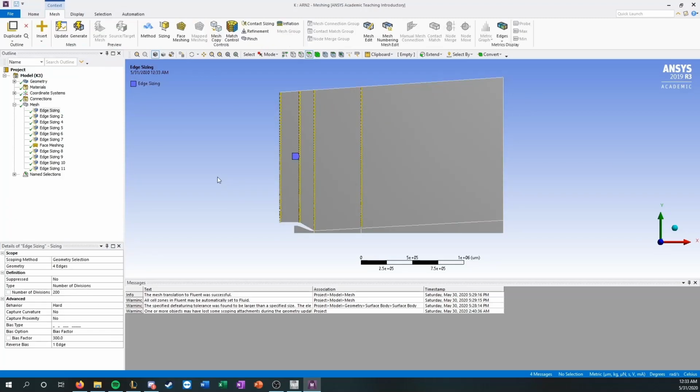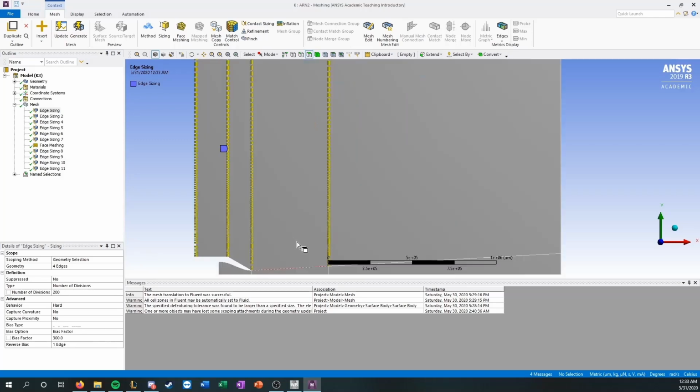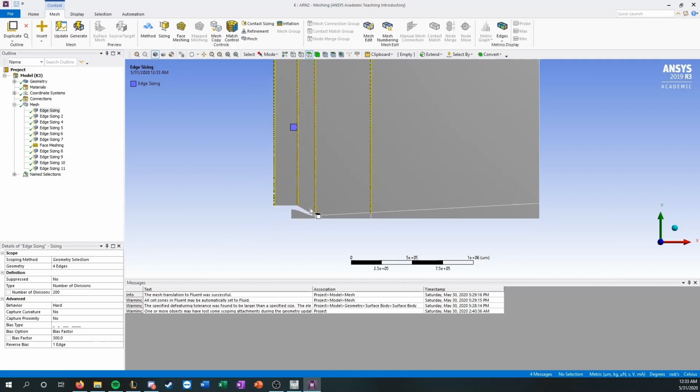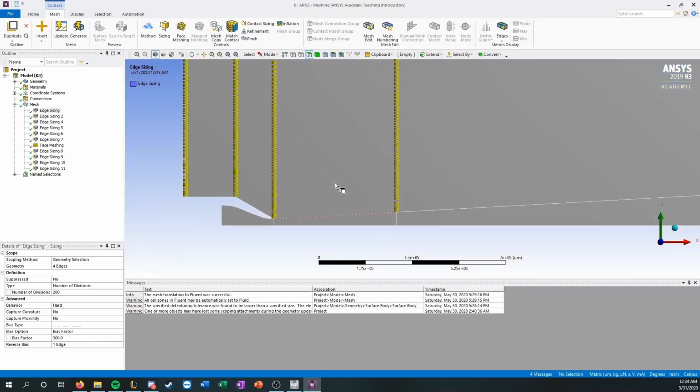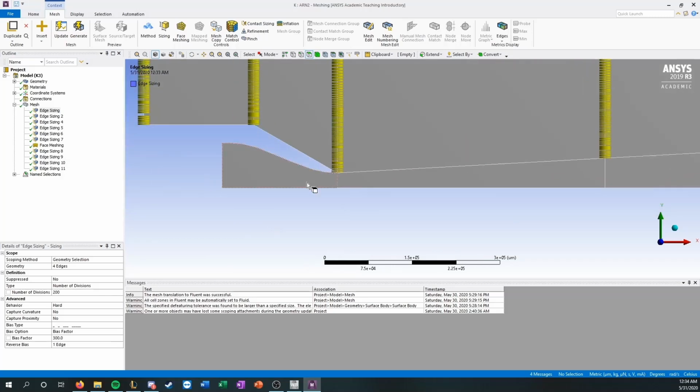Remember, when you're meshing, you have to think about your regions in terms of quadrilaterals, because for face meshing or a map mesh, you want to think of a region being divided this way and then divided this way. So I divided all this way, and I make this bias that you have to play around with, such that I focus on this region the most, because this is the supersonic region or the compressible region.